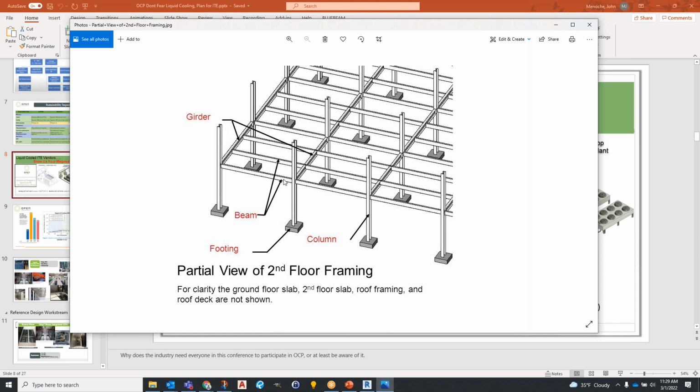But in reality, if you are being smart about it, let's say that this deck right here, which is on the second floor of this building, is designed for 250 pounds per square foot. That is across the entirety of that. You can put something on average that's going to weigh that, right? But if you're a little smarter about it, you know that you can put a lot more heavy things right near the columns or right at a girder. And so that is engineering.